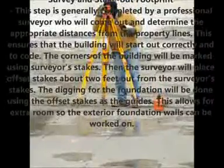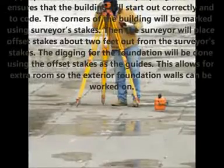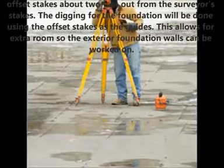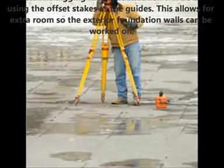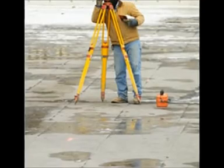Then the surveyor will place offset stakes about 2 feet out from the surveyor's stakes. The digging for the foundation will be done using the offset stakes as the guides. This allows for extra room so the exterior foundation walls can be worked on.